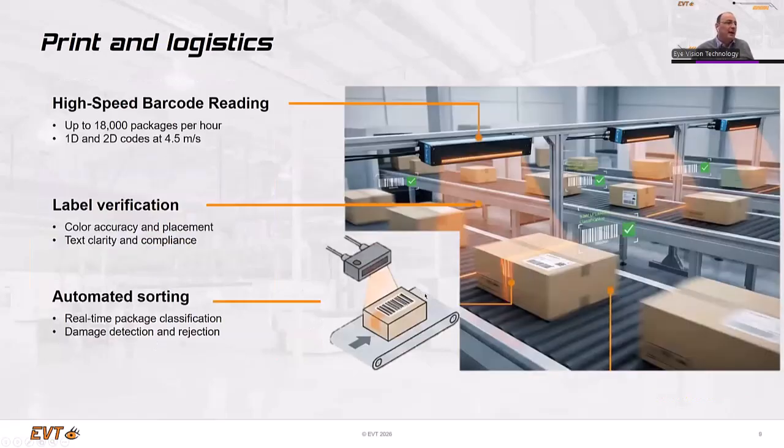Another application where, of course, you can also use 2D cameras, but maybe a line scan camera is a good option, is because it runs endlessly and it's independent of the size of the boxes or of your packaging. You get a very high resolution, which is really good if you want to do code reading, because code reading always depends on a really good resolution to do safe code reading. And of course, these production belts or handling belts, however you name it, they never stop.